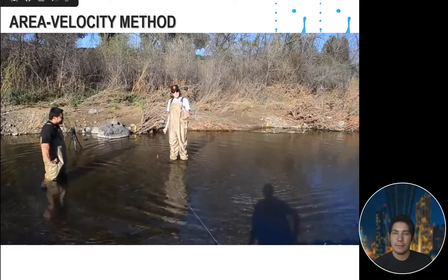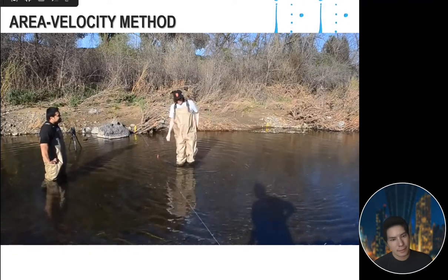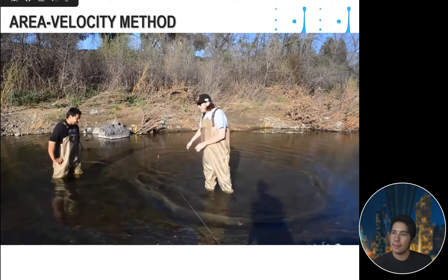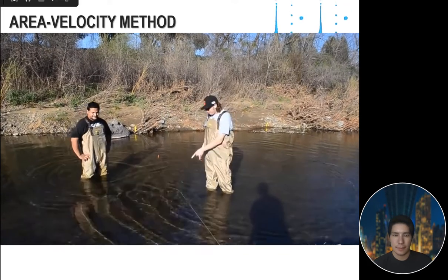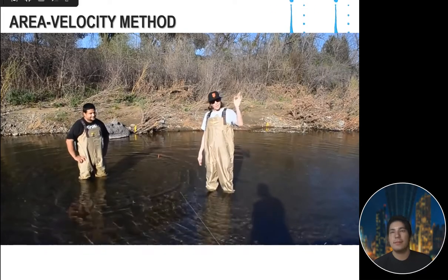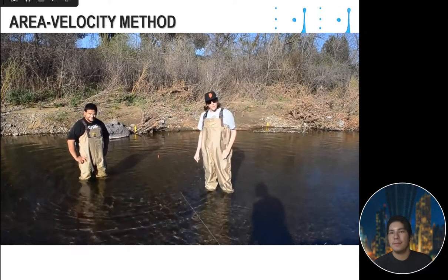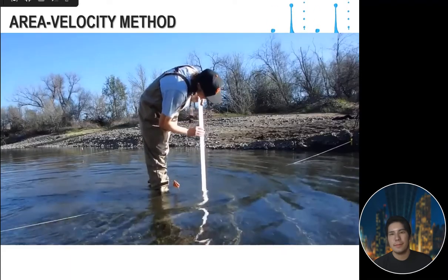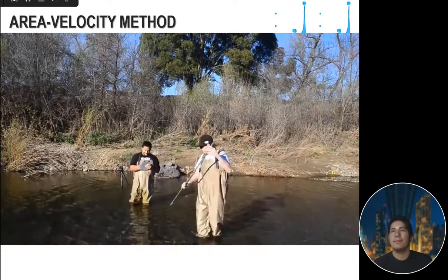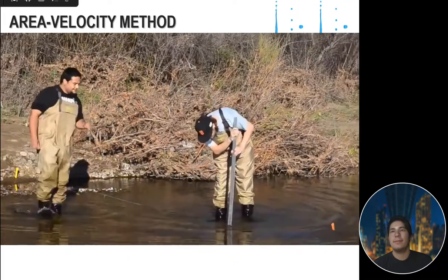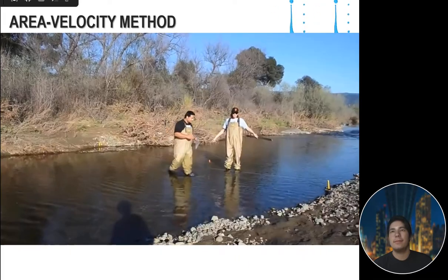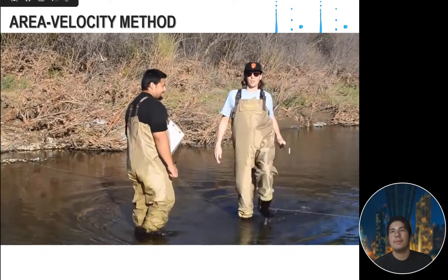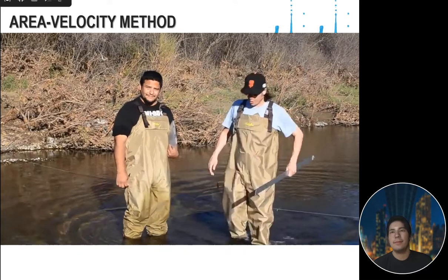That's going to help us to get the average depth of the creek by using a yardstick. Once you have both of the lines marked, we're going to go back through, check the depth at each of these, and write it down on the handy EPA stream flow calculation sheet. Now we're going to go to each one of these 1/4 intervals and check the depth of the creek so that we can take a composite average that's later on used in the calculation. And then obviously each of the stakes at the ends are zeros. We'll get deeper into the calculation once we've actually timed the orange.